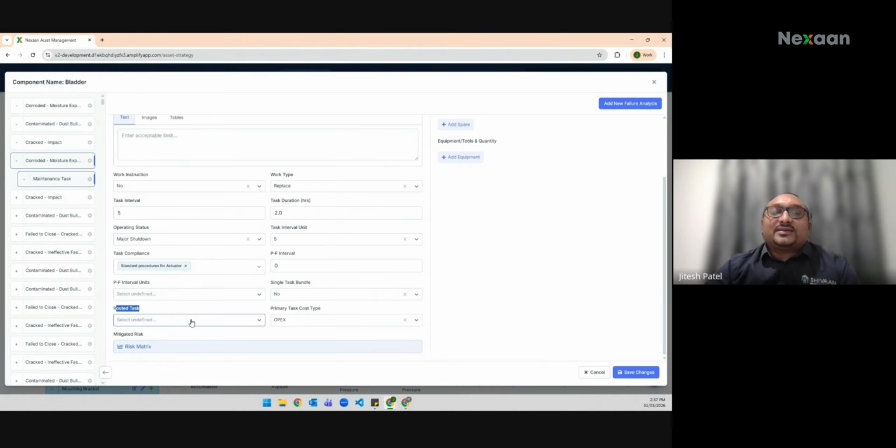So we've got our assets in this example at functional location level 5s. If you need a routed task or a bundle that is above level 5, and you want someone to go and grease multiple motors of various different assets, then you can choose this as a yes, and that will be a separate bundle, which will be seen when we come into the task bundling module, and it will be packaged or bundled at a level higher than an asset, ensuring that it's captured all the routed tasks within the same level that we define.